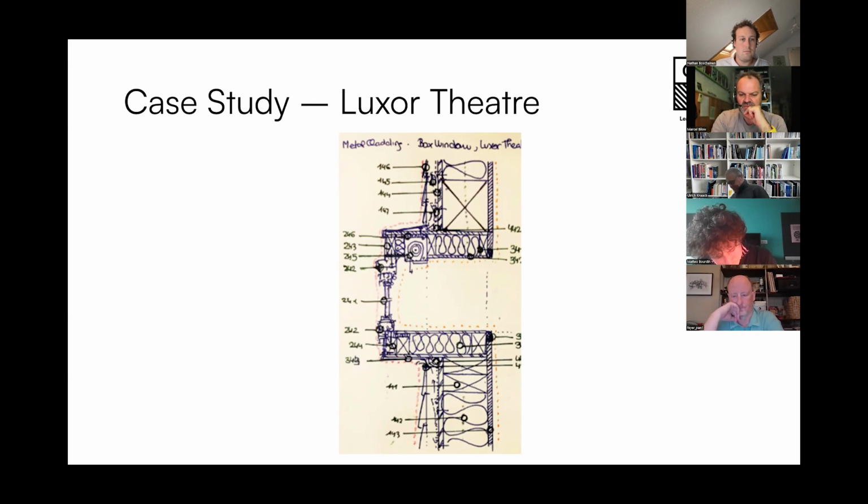Yeah. So this would mean that you have sort of an opening horizontally, fins coming out of the box, and then you make the window inside. That might not be the case. That might actually be made in a different way, that a pre-assembled window frame comes in front of it, and then you later fit the overhangs and the inside cladding with insulation.